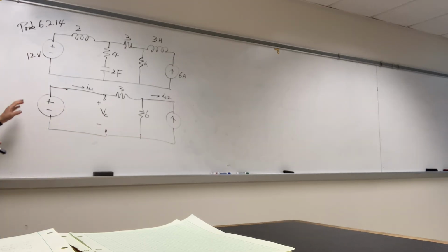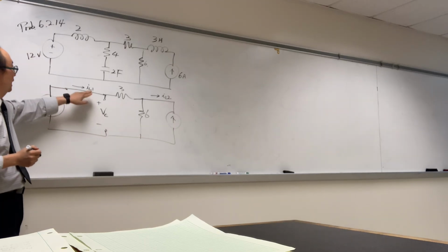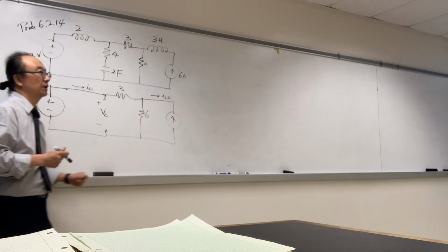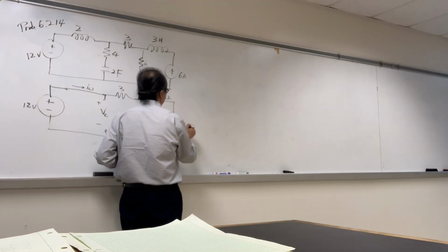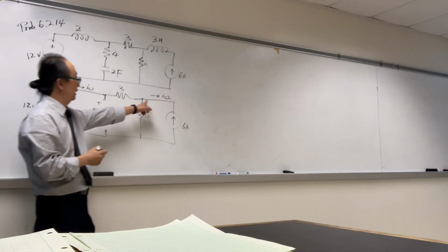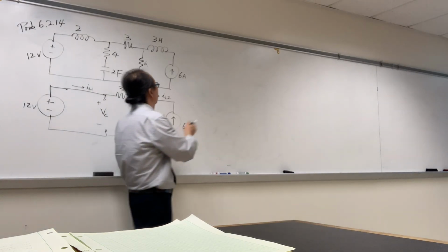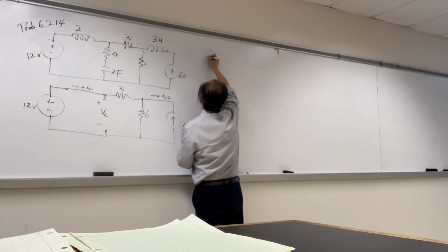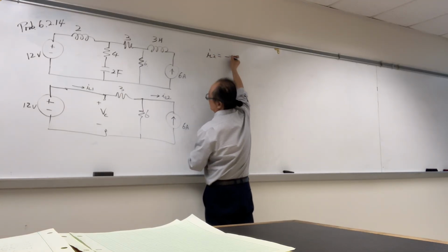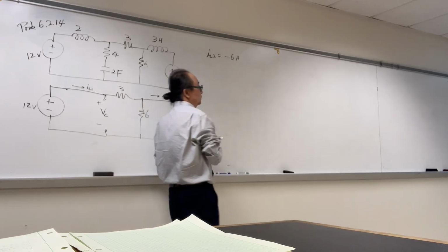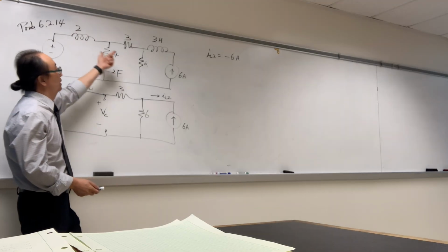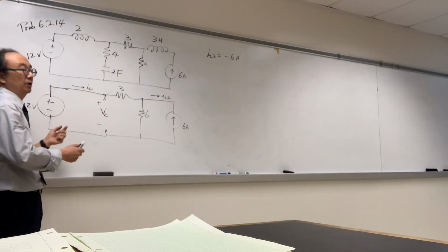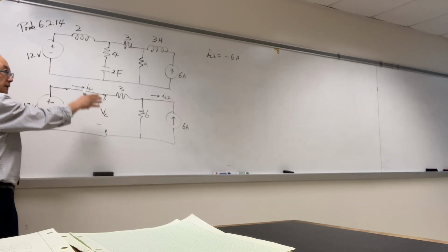So our objective, our job is to find the VC, IL1, IL2. That way we can put it into the W equation and find the energy in joules. So now what do you want to do? We already found the IL2, right? IL2 is opposite of this guy. Therefore, I'll just write IL2 equals negative 6 mA. Done. All the time in chapter 6, chapter 7, under DC conditions, the current direction of the inductors always goes from left to the right, top to bottom.